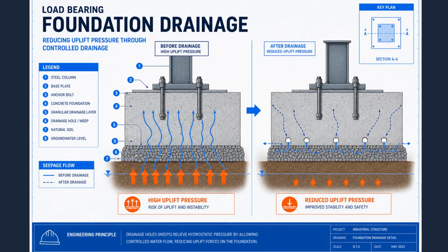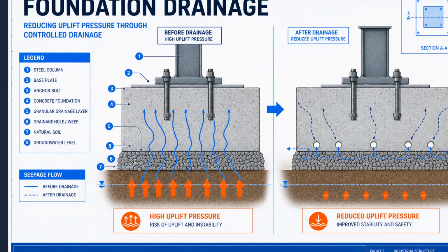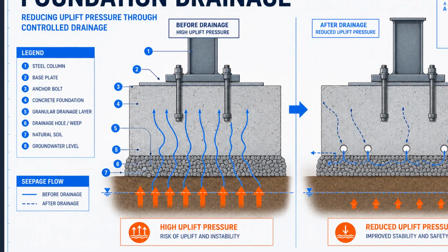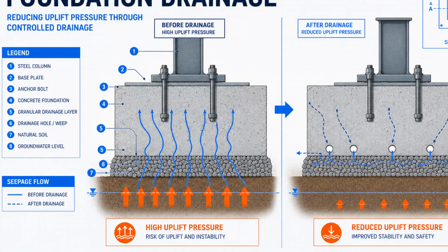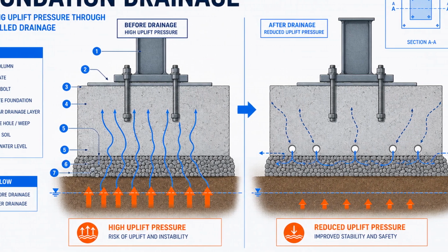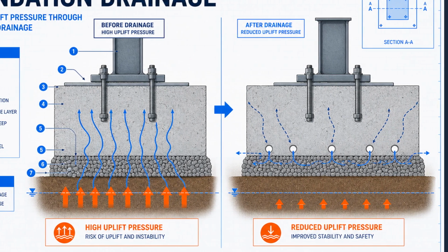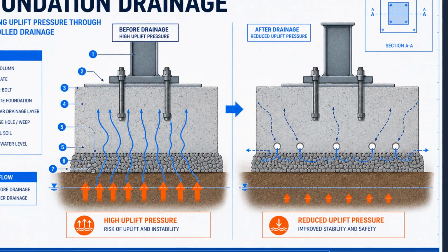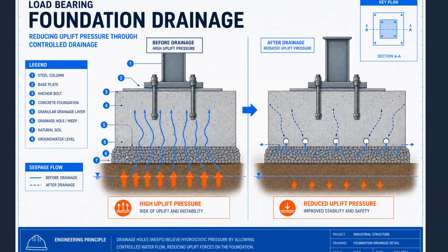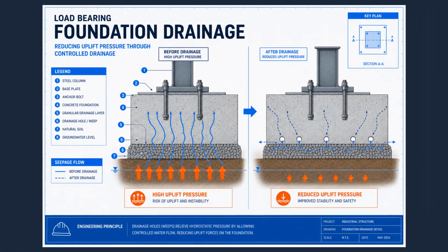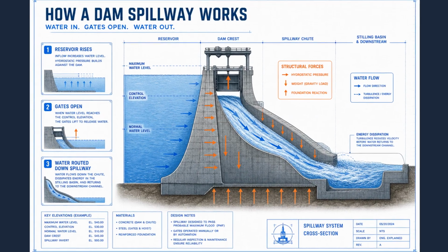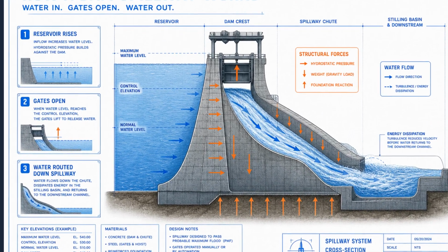Designers must prevent sliding at the base and uplift pressure under the dam. Drainage galleries, grout curtains, and foundation treatment reduce seepage and pore pressure so friction and shear resistance remain reliable over decades.